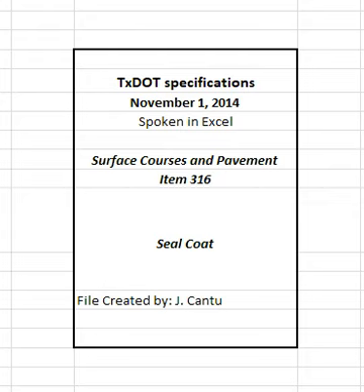4.8.4 Test strips. The engineer may stop asphalt application and require construction of test strips at the contractor's expense if any of the following occurs. Non-uniformity of application continues after corrective action. On 3 consecutive shots, application rate differs by more than 0.03 gal per square yard from the rate directed, or any shot differs by more than 0.05 gal per square yard from the rate directed. The engineer will approve the test strip location. The engineer may require additional test strips until surface treatment application meets specification requirements.